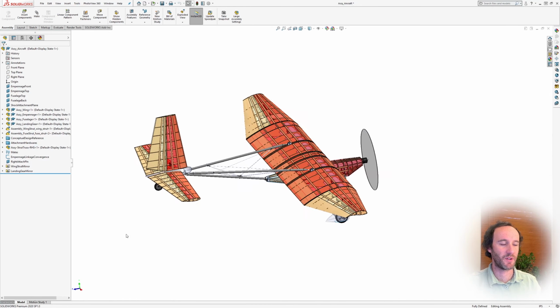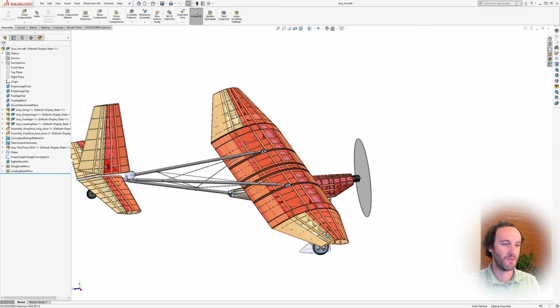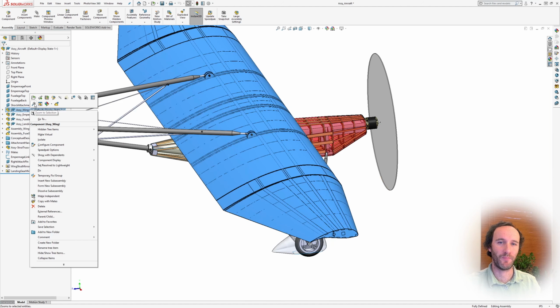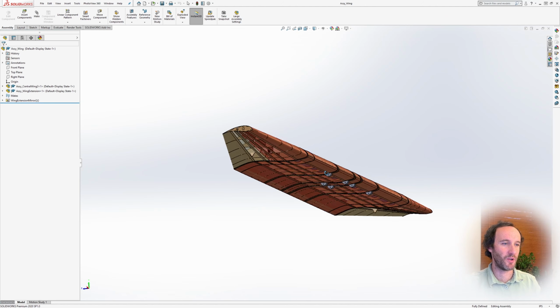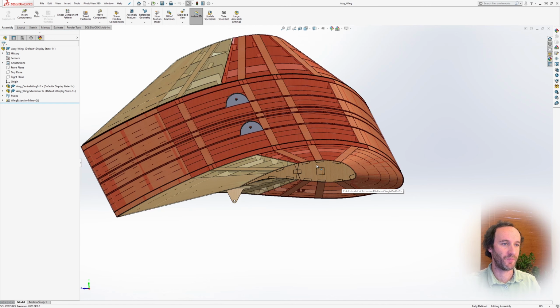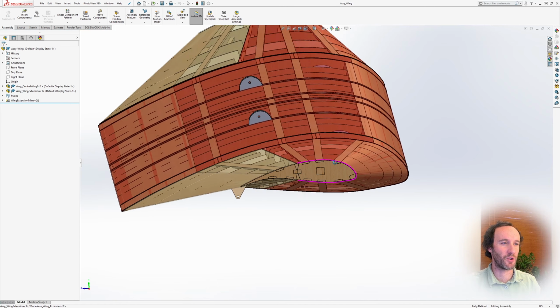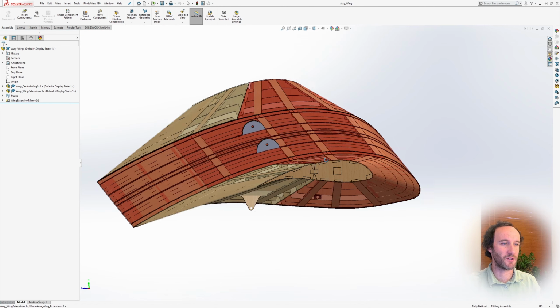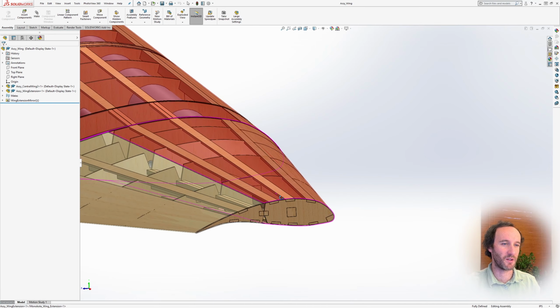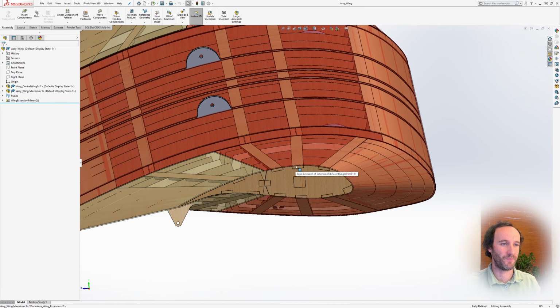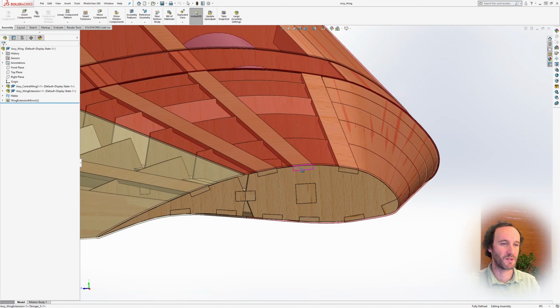Another thing specifically for wings: if you have a trapezoidal planform and just geometric washout for a tapered wing like this one, then you don't necessarily need the wrap feature, because along constant percent chord lines there is no curvature. So you can arrange the stringers along those percent chord lines and then they're all straight, and you can just use an extrude with a twist.